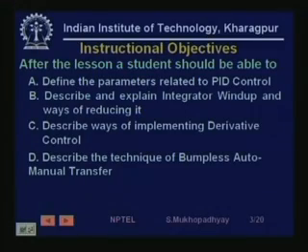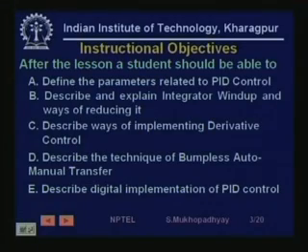We will also describe one technique of bumpless auto manual transfer, that is when the control is transferred from auto to manual or manual to auto, so that it can happen without any shock to the process. And finally, we will describe digital implementations of PID control. So in other words, we are going to look at various practical aspects of PID control today.